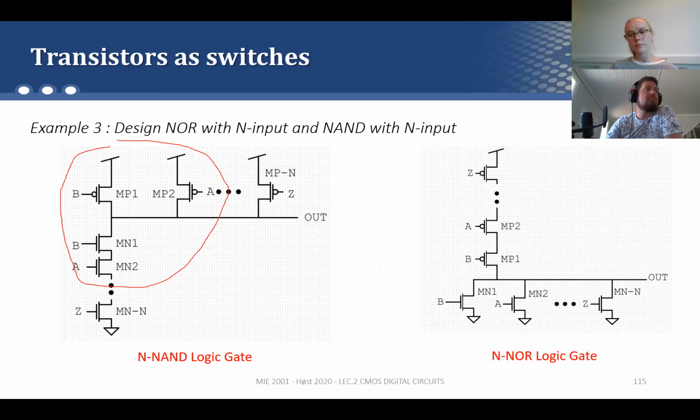The same thing also applies to the NOR logic gate. In this case, if you want more inputs, you have to add more PMOS in series and more NMOS in parallel. Okay.